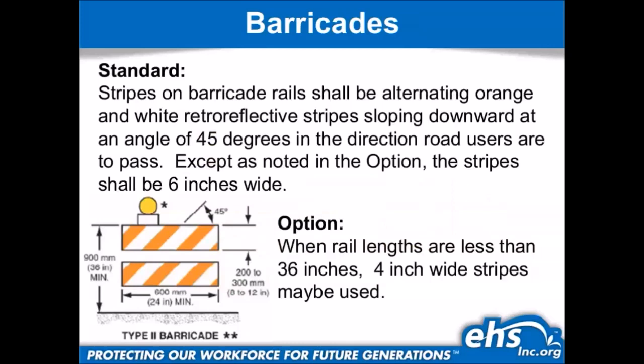The standards basically say for the reflective material, and think about your cone inventory and your signs and everything else: your reflective material on your vests, signs, cones, whatever the equipment is, should be seen at night at a distance of 1,000 feet by someone driving with 20/20 vision and legal with their vehicle with legal high beam headlights. So the reflective material should at least reflect back at that distance. If it's not, maybe it's time to replace the vest. Maybe it's time to replace the cone or the sign, right? You want these things to be seen at a distance.